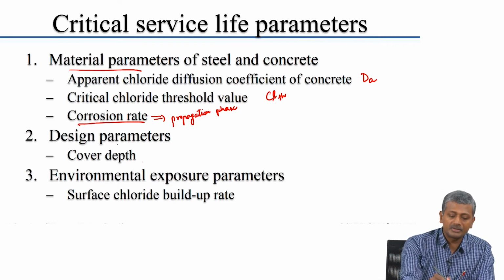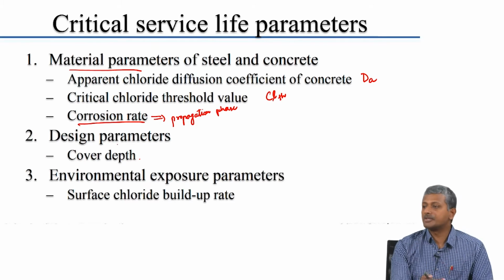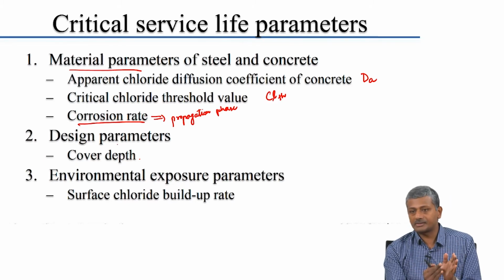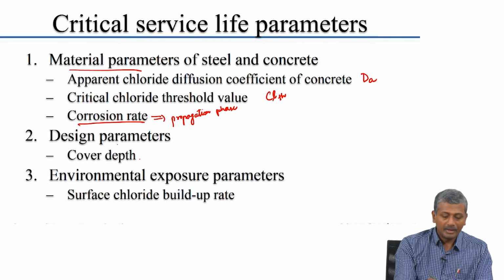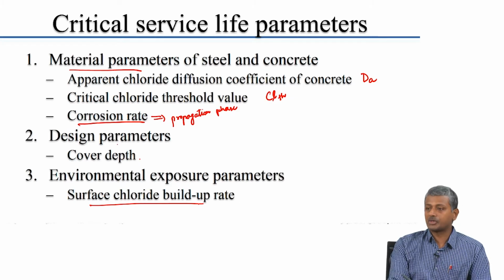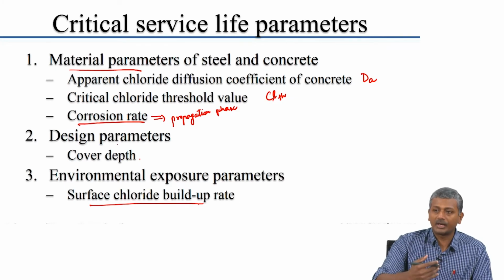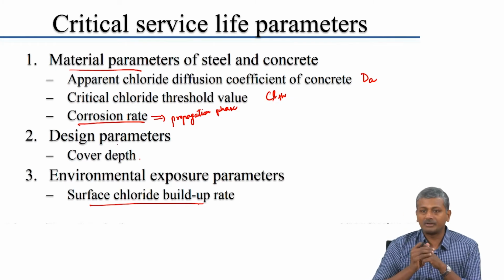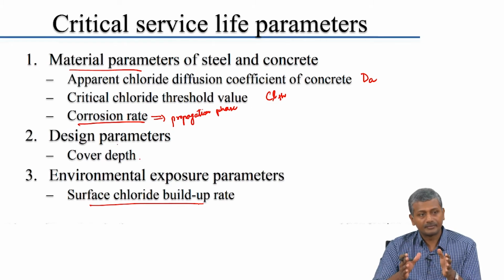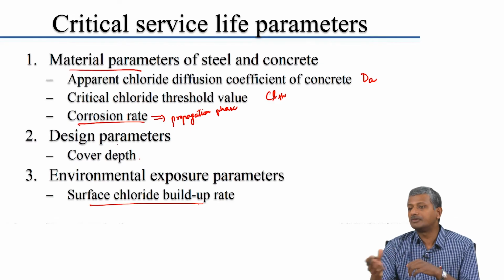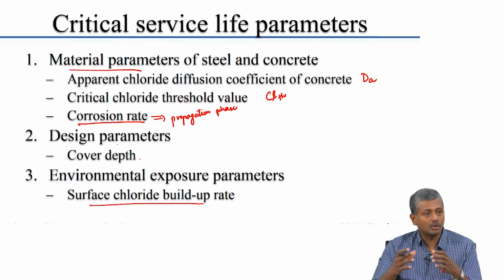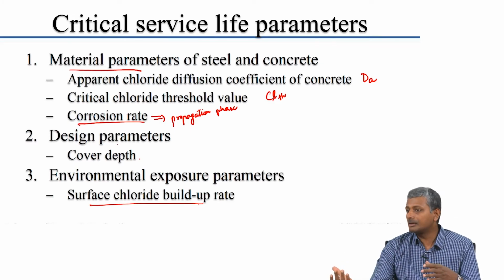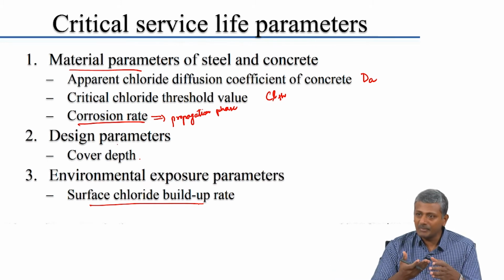Now, design parameters include cover depth, because you can always vary the cover depth to check whether your design is satisfying the requirement or not. And then the other aspect is the environmental exposure parameter. How soon does the chloride build up at the surface of the concrete? The critical or surface chloride build-up rate will depend on the kind of environment your concrete is in. For example, if your concrete is directly exposed to marine conditions, then the chloride is immediately building up in the